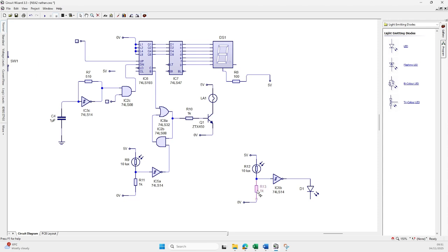I'm going to put a resistor on as well, down there. Remember, the resistor wants to be less than 1K. Let's go 220 ohms, and then stick it down there. So I can now test that. That's a standalone subsystem, and it's also ready to be tested. You might want to also put a voltmeter on there, but I can do that later.